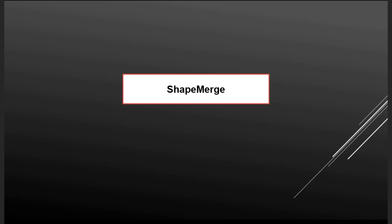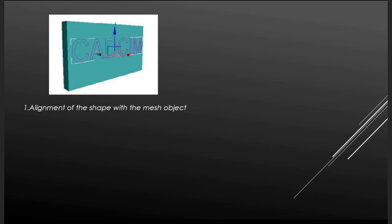Shape Merge. In a Shape Merge object, the shape is either embedded in the mesh object or subtracted from it. To create a Shape Merge object, first you need to create a mesh object and a shape, and then align them. Next, select the mesh object and choose the Shape Merge tool from the Object Type rollout of the Compound Objects.